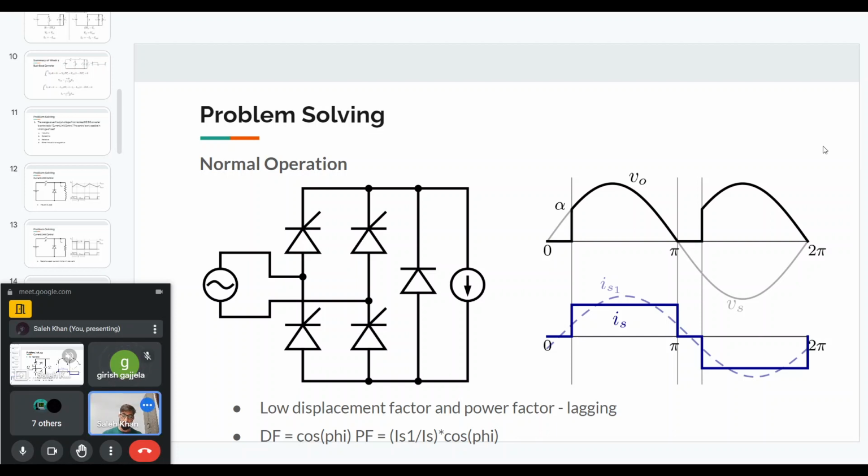Yes, there is slight difference between them. I guess when you are considering the reactive power, you just go by the definition of the reactive power. So that will be the RMS voltages times the sine of the angle. And similarly, the real power will be the product of the RMS voltages times the cosine of that angle.